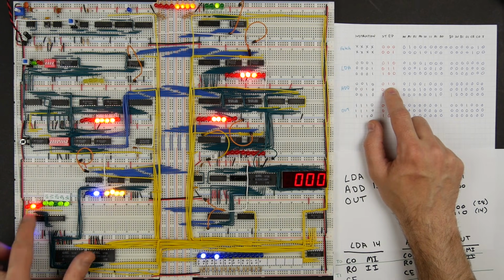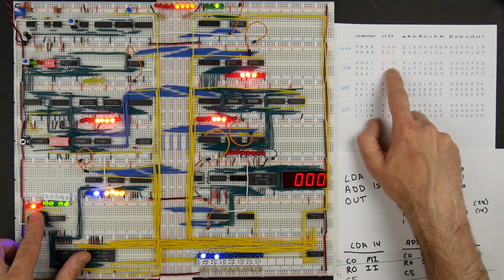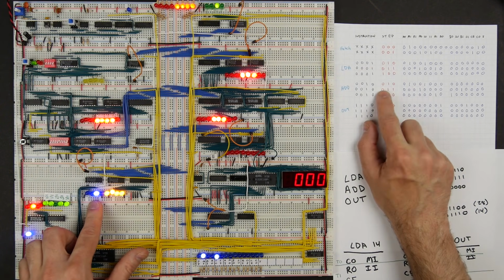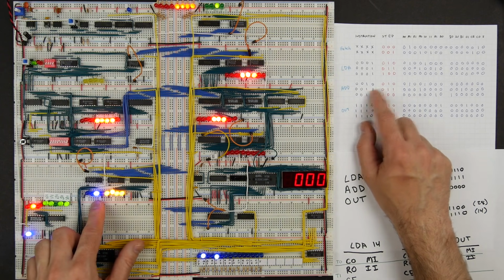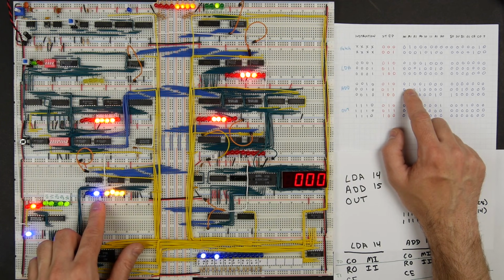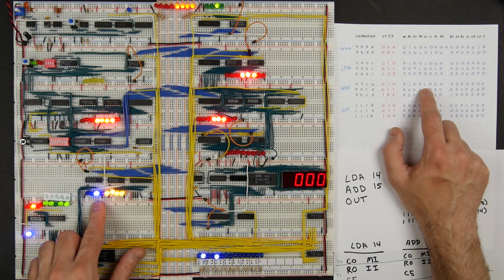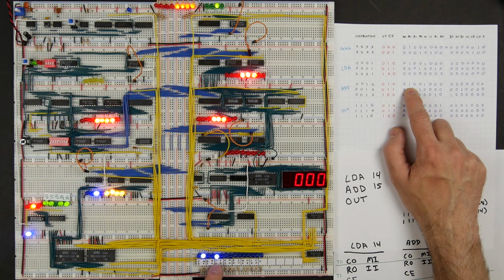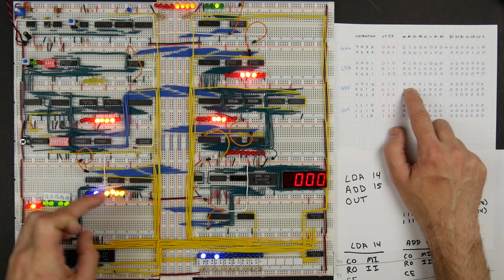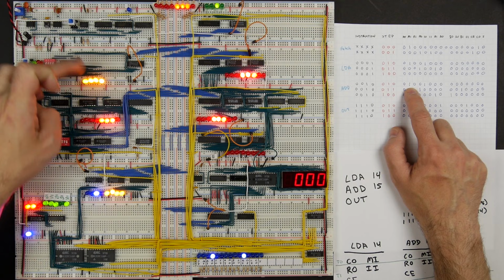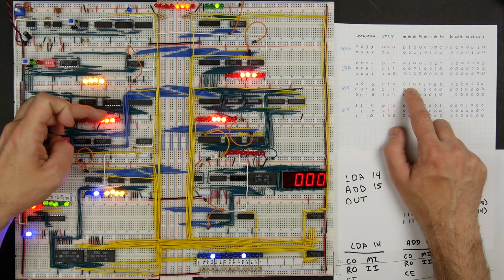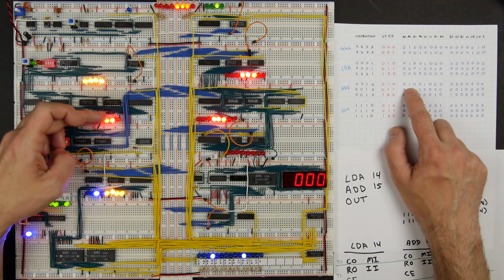So now we're on step 2, 010, but instead of 010 and having the load A command here, we now have the add command here in our instruction register. And so we're going to do something different. So here, this time we're going to do instruction register out and memory address register in. And so that appears to be what's showing up here. So we got the EEPROM programmed right. So it's going to take, again, this address from the instruction register and move it into the memory address register. So now we can get at the contents of memory, which is this 14.